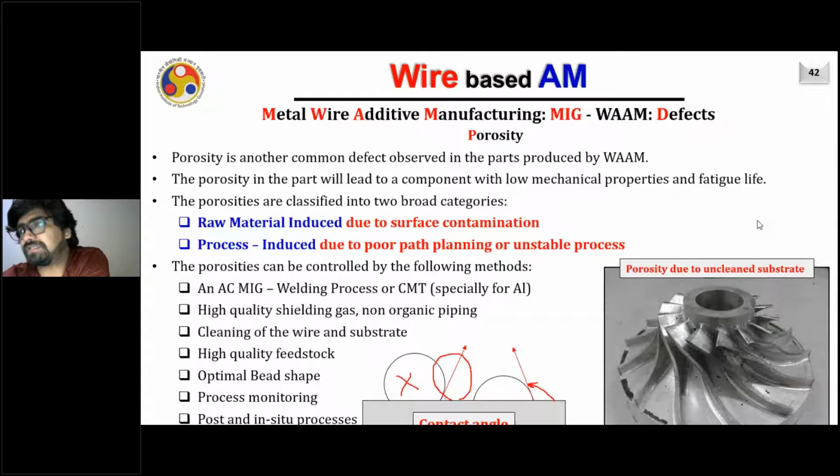In that case, yes, you will not be having a sufficient melt pool, and in that case, preferably you should go with a cold metal transfer type of process. But if sheet metals already have porosities, I'm not sure how you can eliminate them. So what we can do, you can unmute and ask. I think I'm not able to understand your question completely.